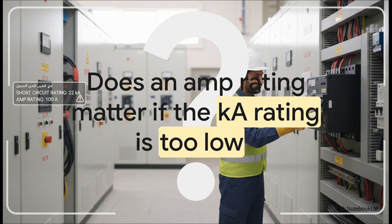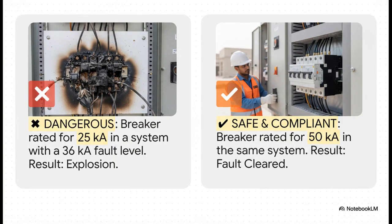Now for a huge safety check that honestly gets overlooked way too often. We all obsess over the amp rating of a circuit breaker, right? But that's only half the picture. The really critical question is about its short circuit rating. Look, this is a life or death detail.